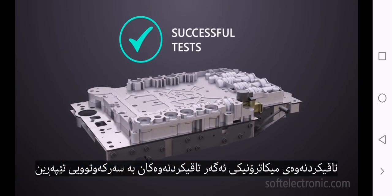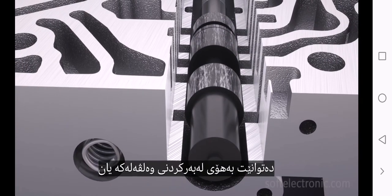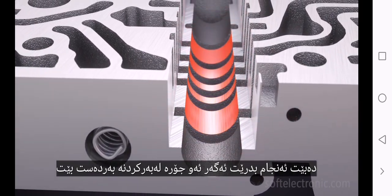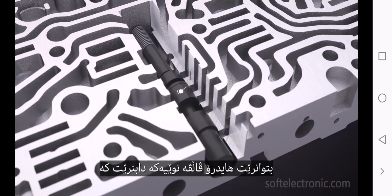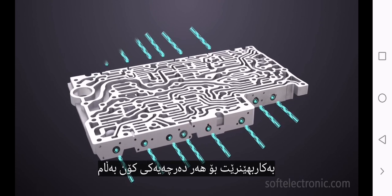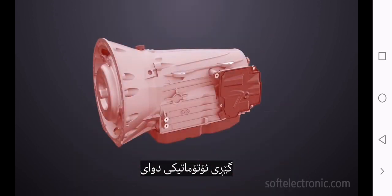If the tests pass successfully, the valve body is assembled to the control unit and the mechatronic is mounted in the gearbox. If the tests show deviation from the working parameters of the valves, this could be due to wear of the valve or the valve seat. Correction of the valve seat must be made if such wear is available. The process is also called reaming. With a specialized set of reamers, the damaged valve seat is processed so that the new hydro valve can be installed, which is of a larger repair size. That process can be applied to each worn-out opening, but only once. Repeating the procedure on a previously repaired opening may result in malfunctioning of the automatic transmission.